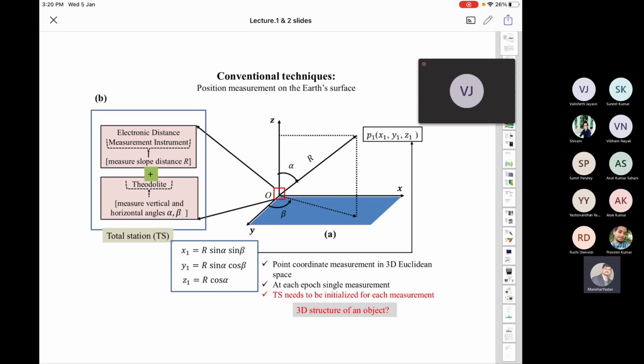If you want to exactly model the four sides of a building and the roof of the building, let's say you select one side of the building, which is 4 meter by 6 meter. On that surface, you need to select uniformly distributed target points, so that once you calculate their coordinates, you can mathematically generate a surface that can actually represent that building side. Getting the point?